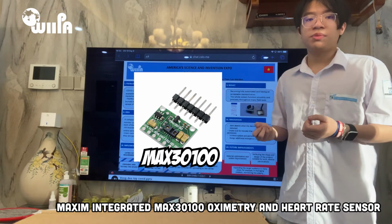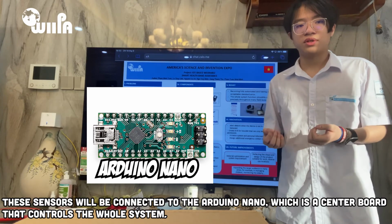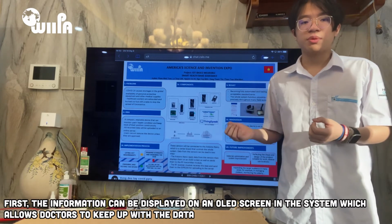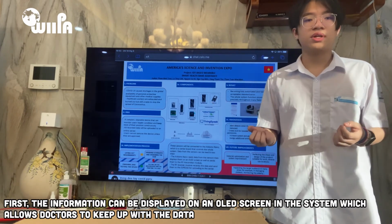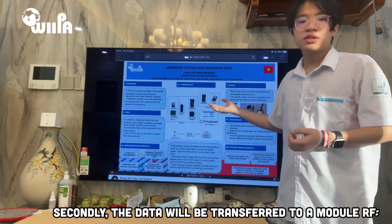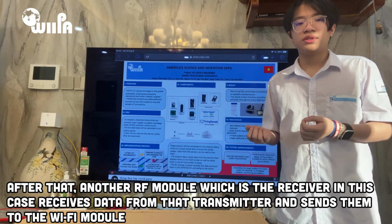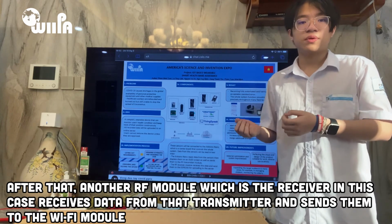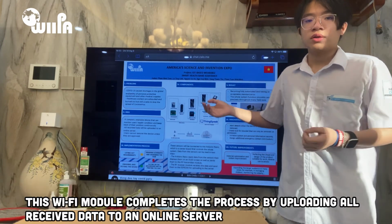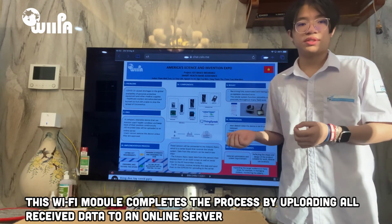The sensors will be connected to an Arduino Nano, which is a central board that controls the whole system. Data from the sensors can be read in 2 ways. First, the information can be displayed on the OLED screen in the system, which allows the doctor to keep up with the data. Secondly, the data will be transferred to a modem RF. Another modem RF receives the data from these transmitters and sends it to Wi-Fi modules. These Wi-Fi modules complete the process by uploading all received data to an online server.